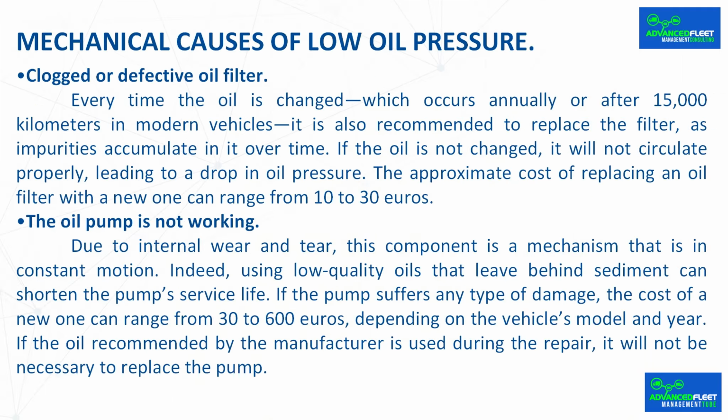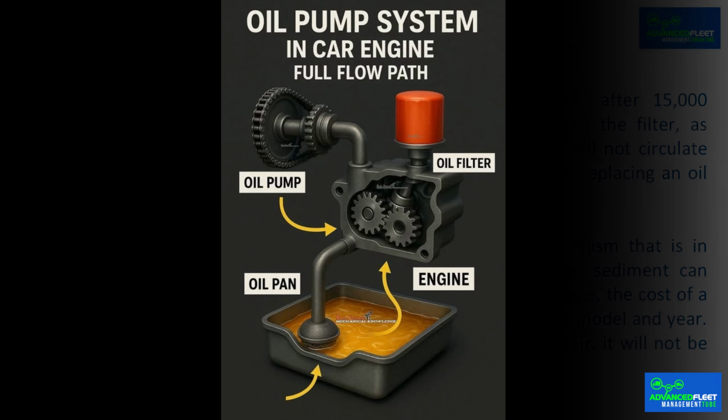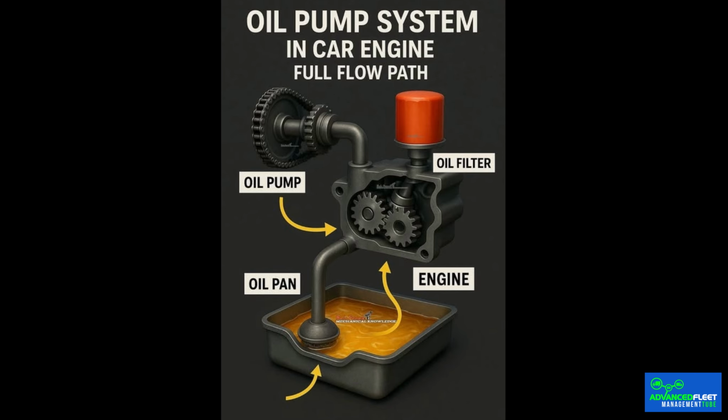The oil pump is not working. Due to internal wear and tear, this component is a mechanism that is in constant motion. Indeed, using low-quality oils that leave behind sediment can shorten the pump's service life. If the pump suffers any type of damage, the cost of a new one can range from 30 to 600 euros, depending on the vehicle's model and year.